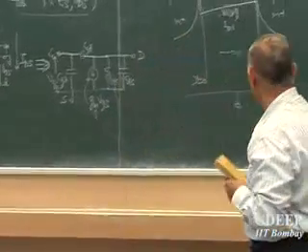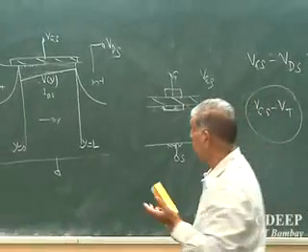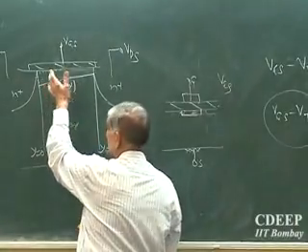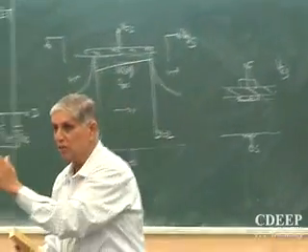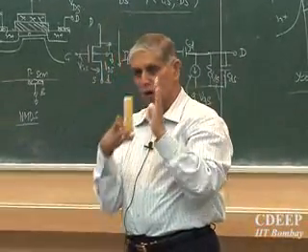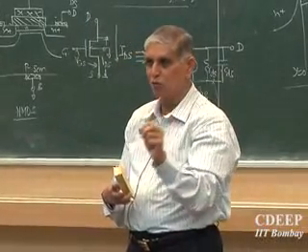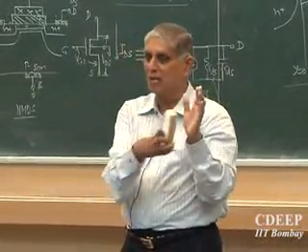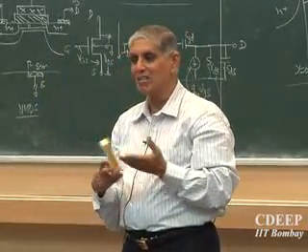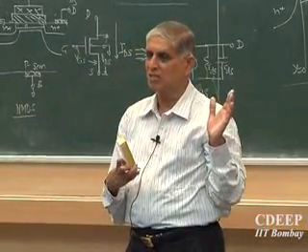This is something interesting. And this will now tell us how, if I want to calculate the current or the drops, I must take care of this voltage variation, because in a capacitor I solved it very easily, saying same voltage. Now at every point I'll have to solve. So something I'll have to solve at y equal to 0, something between this, y, and then maybe I'll sum it up or integrate it out to say, okay, totally how much IR drop I actually got. Is that clear?